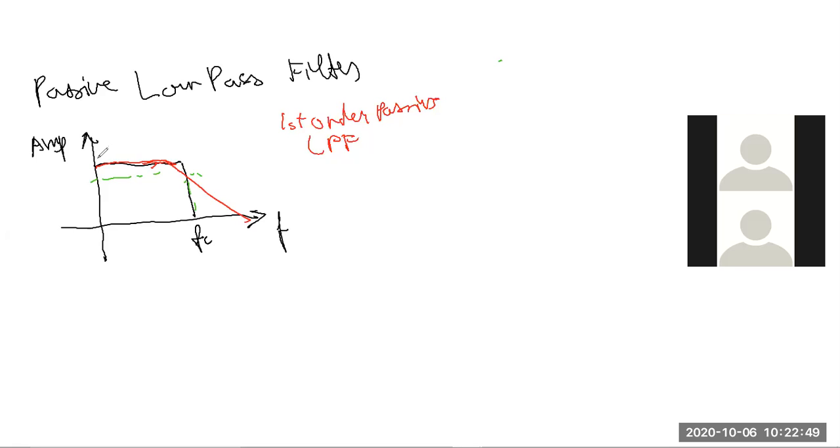3 dB, yeah. 3 dB is in the decibel unit, but in a normal ratio number, how much is this? 0.7071. Or in rational number, this is 1 over square root of 2. Okay, so that is the ideality.